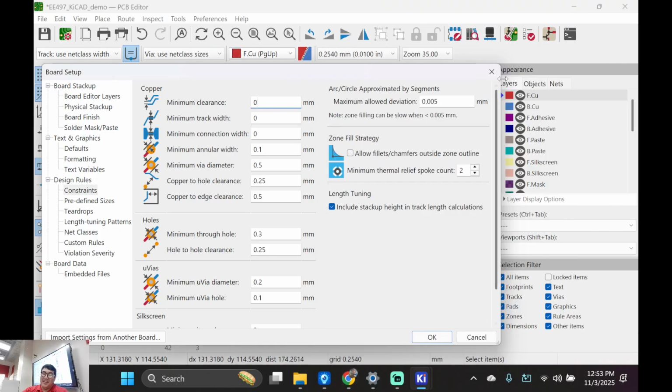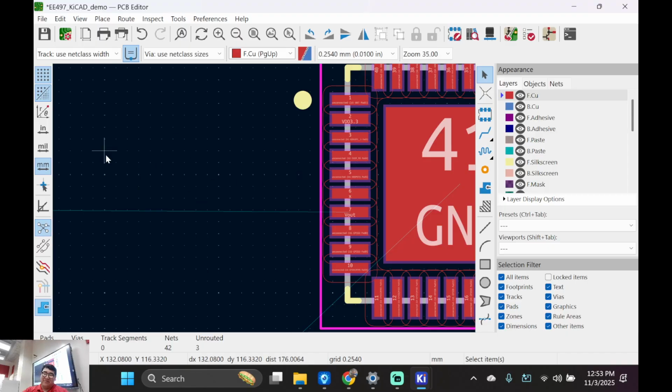So here's another thing, and you're gonna be bothered by this all the time when you're designing your PCB and picking out components: people have different standards. If you go with some manufacturer not in America, they'll use millimeters. And if you use American, they go with mils. Mil stands for milli-inches. So 0.001 of an inch, okay? So 1 mil is 0.001 of an inch. So thousandths of an inch.